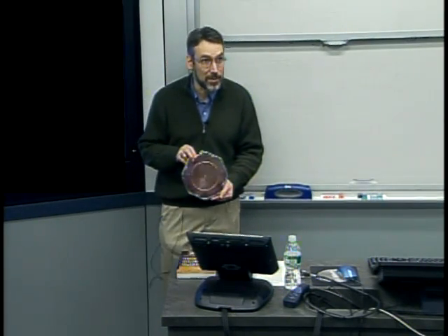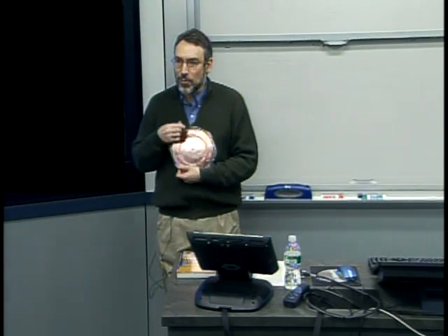The second was chip-to-chip stepping. So in fact, the photolithography equipment is typically called now a stepper because it's imaging one field, maybe one chip. There may be more than one chip in each field, but I'm stepping through in order to get the control and be able to achieve the alignment on one chip at a time. And in the most modern equipment, in fact, they don't even image the whole chip at one time.